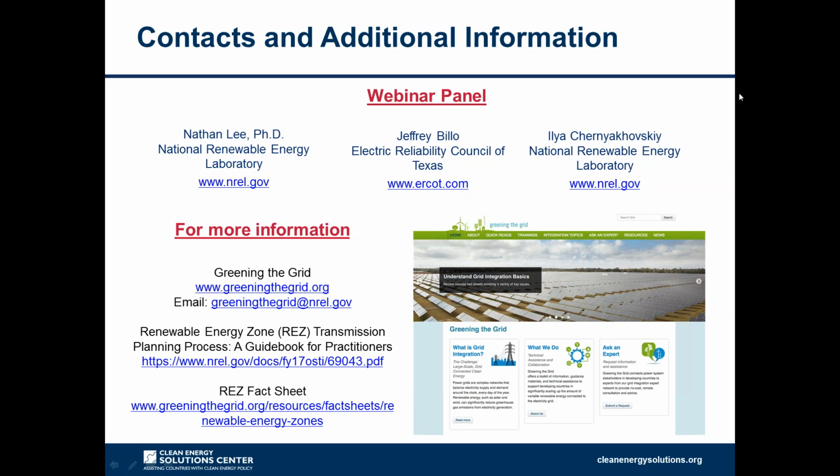The main consideration was that the Public Utility Commission had given us these scenarios with certain megawatt targets for each of those scenarios. And we really developed the plan and sized the transmission based on those scenarios. Now, we also, as any good transmission planner would do, looked at future expansion capability and looked at areas where we may be planning for a certain amount of megawatts at this time, but recognize that there's a lot of potential in this area. And so we did have an eye towards, well, what's our expansion path? What's our next transmission system upgrade after this one? And that went into sizing the facilities.